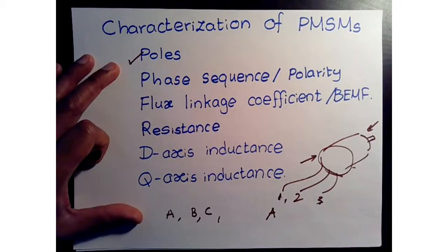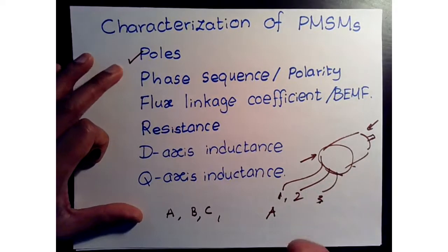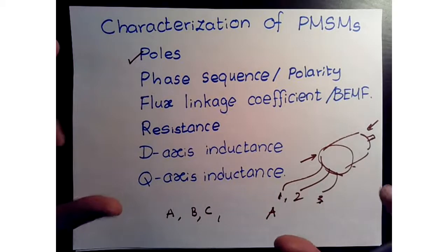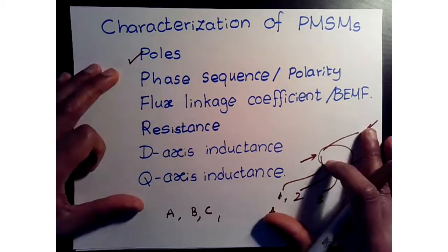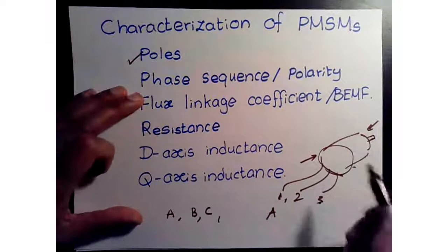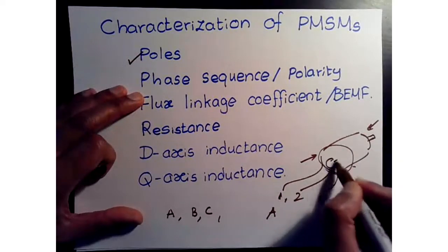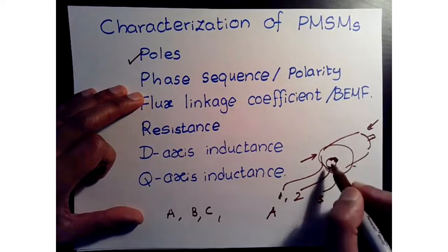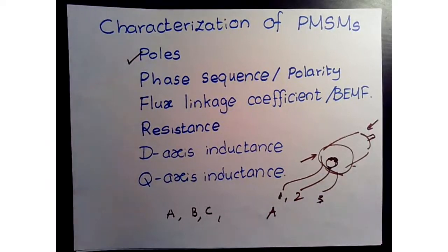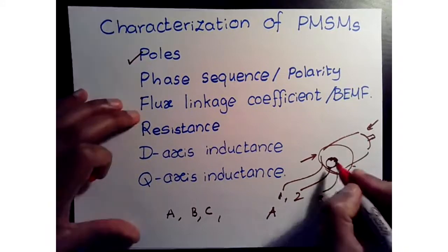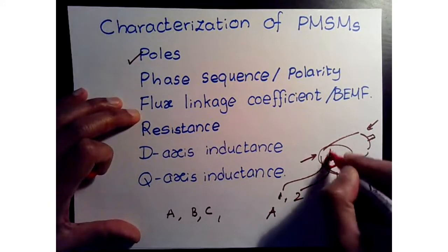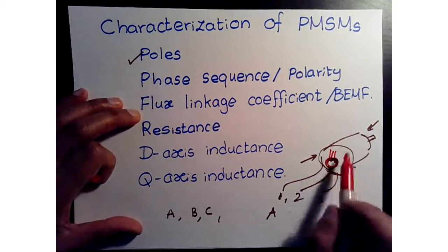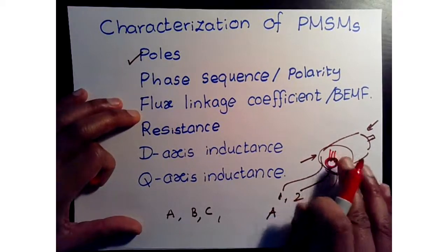Okay, and it is up to you to choose what that's going to be and what that needs to be. And then typically, a rule of thumb, this is not a very strong rule that I'm forcing you to follow, but typically you will see a motor position sensor. Maybe it's an encoder, maybe it's a resolver, maybe it's a hall sensor that gets mounted here. Let me use a different color for the position sensor. Okay, so we have a position sensor and you have wires coming out. This is basically giving you the position.